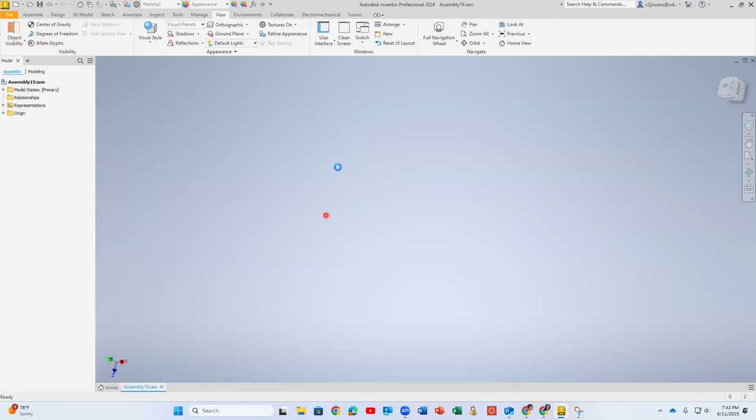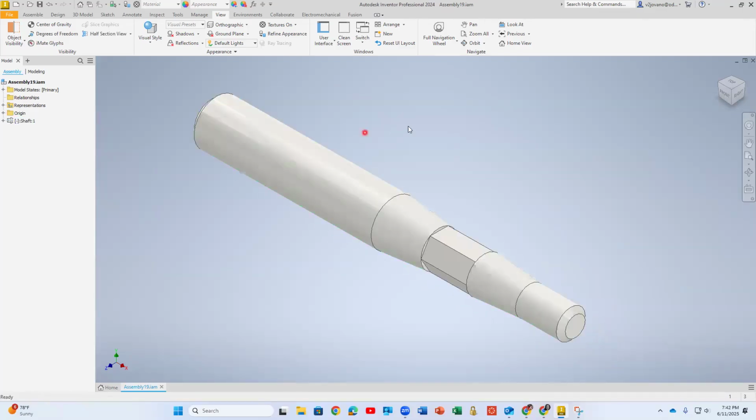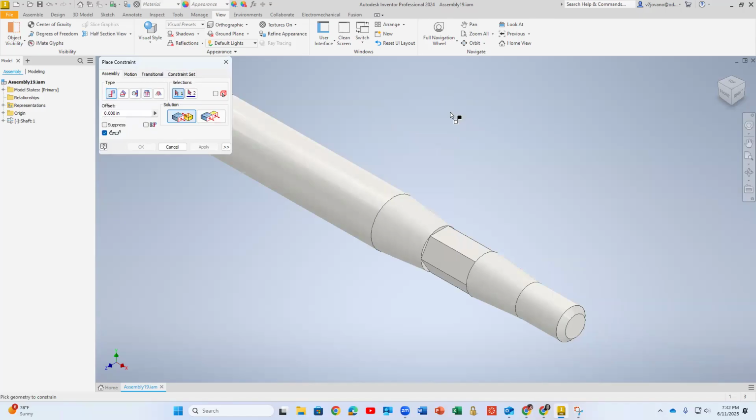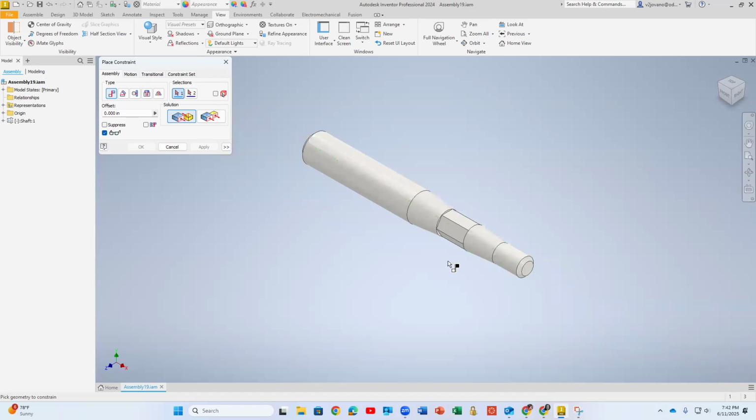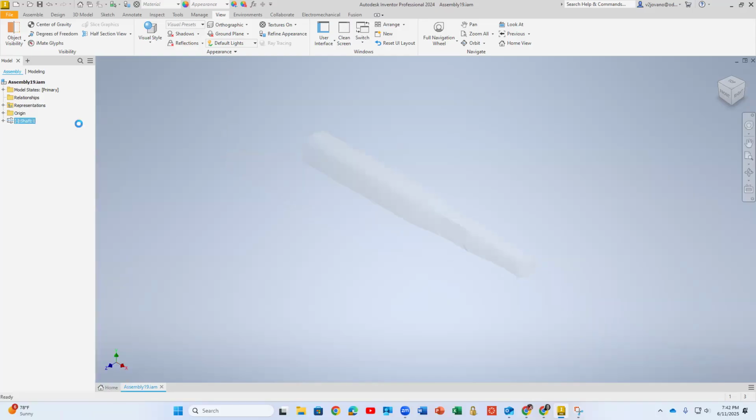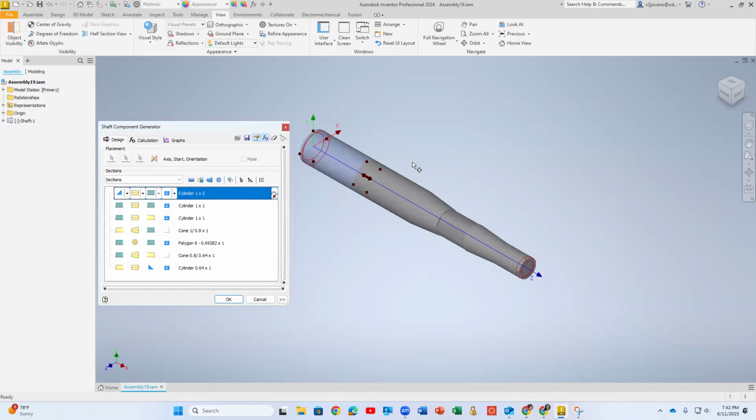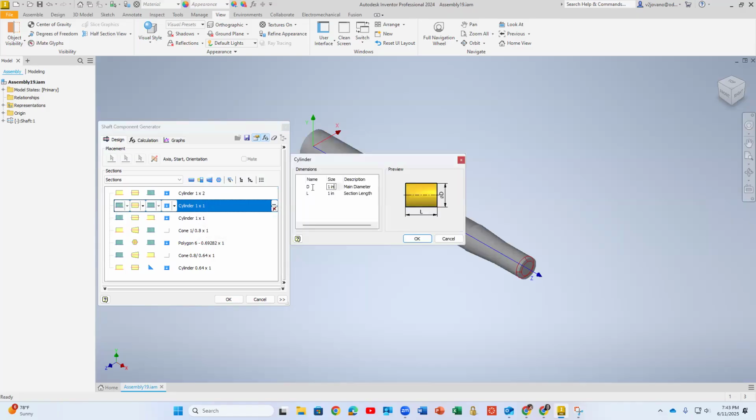And now you can follow these steps to see how you can make some other shaft. So for example, this is the one, and you can edit these parts if you follow all of these steps. See, I just took the big one and I quickly made something. But at the end, if you don't like what you have, you just go edit using Design Accelerator and you can rearrange any of these things, how they look. So now I can easily edit. They don't have a chamfer at the beginning, 1.1. The other one is 1.5. So diameter is actually 1.5. That makes more sense. 1.5 by 3, you see, I'm doing the second one.